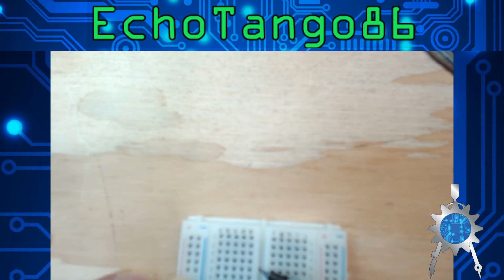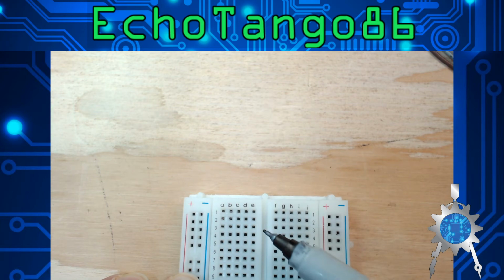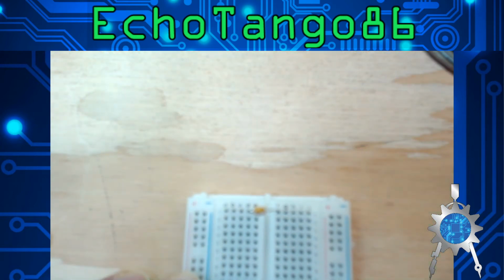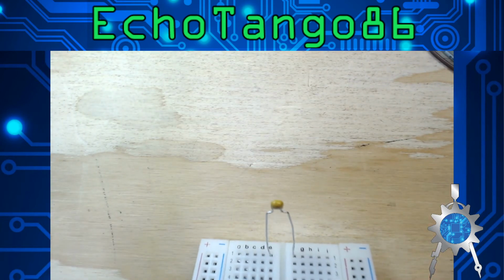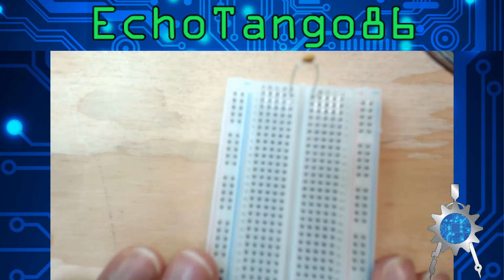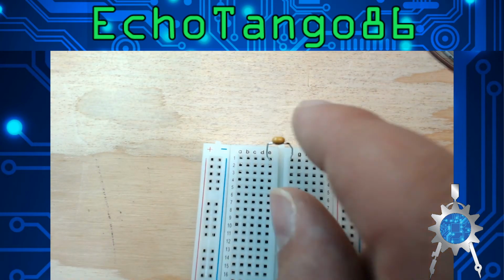Now, this middle area here, and I am sorry that it loses focus, this middle area is your divide. So this side is not connected to this side. A lot of times, what you'll see people do is bridge the gap with a resistor, capacitor, LED, whatever. That is not shorting. That is literally bridging the gap. And so everything goes through the capacitor in the right way. That is acceptable. So that's how a breadboard works. So you can follow along as I put it together.